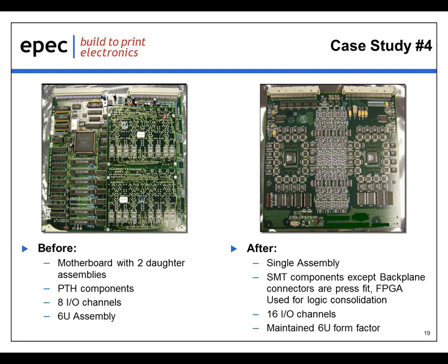Excuse me, let me back up. The issue that drove the cost, the redesign, was the availability of the pin-through-hole components. Most of the parts they were using on there were becoming obsolete in a very short time. So we took the logic diagrams and condensed the logic circuitry, 80% of it, into the FPGA.